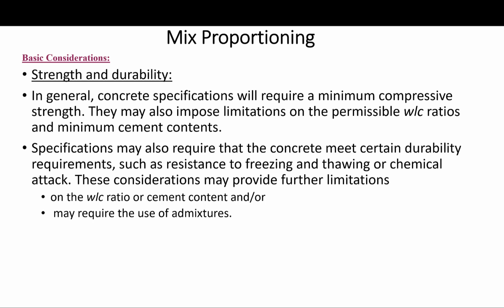The process of mix design involves the satisfactory resolution of all the requirements just described. Since these requirements cannot all be optimized simultaneously, some compromise between strength and workability will be necessary. You sometimes have to give up something in return for something else which is more important.